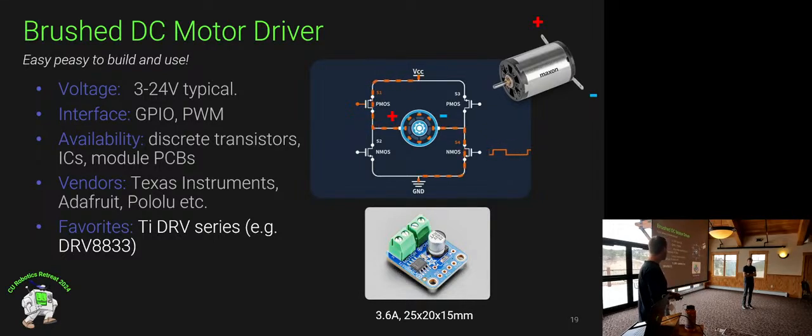Sure. For example, if you wanted more torque out of it and you wanted to draw lower current, then you could potentially gear it such that you're getting more torque out of the motor, but you only need to put a little bit of current in. So you can definitely do things mechanically as well to make your life on the electrical side easier. Generally, the faster the motor's spinning, the less current it draws because of what's called back EMF. We don't have to get into the detail, but basically the current goes down.